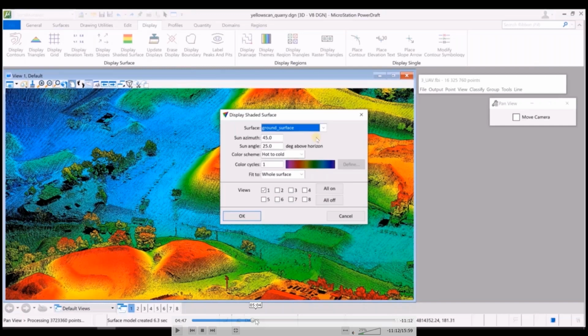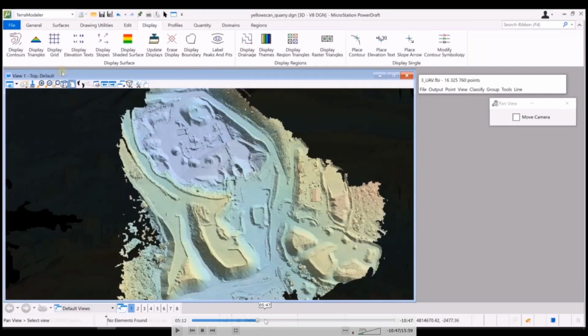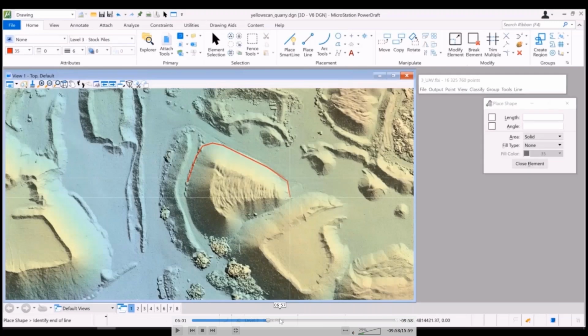Similar to how I showed creating the surface for ground points or the contour points, you need to do the same for the ground surface, or use an already created one, and then have theoretically the bottom surface. Triangulation of that surface can be done from the line around the pile or around the object for which you want to calculate the volume.